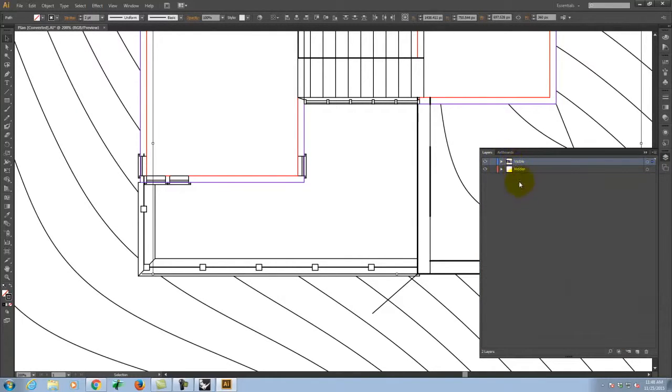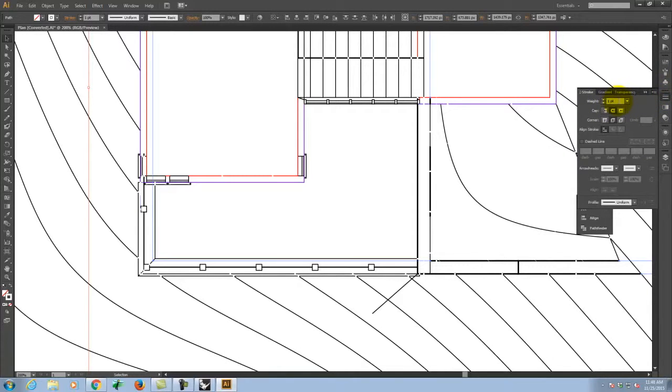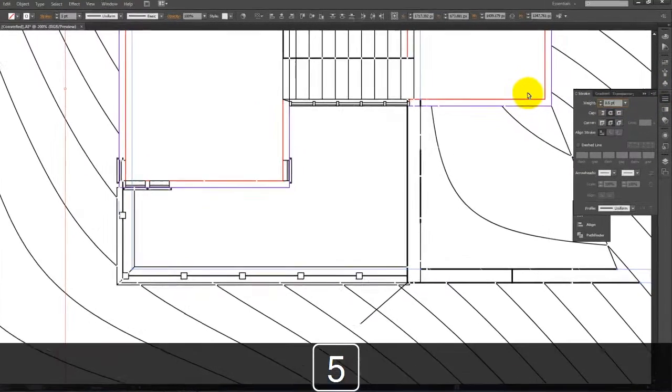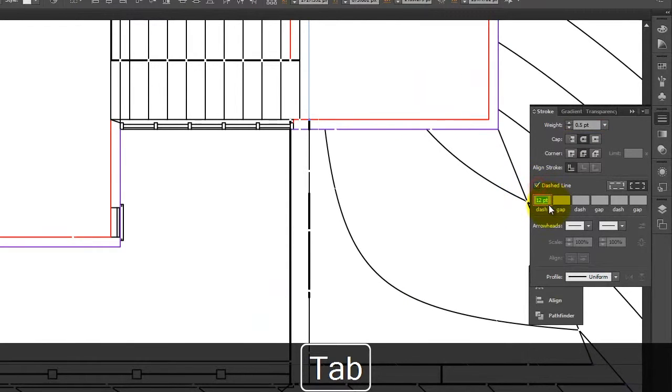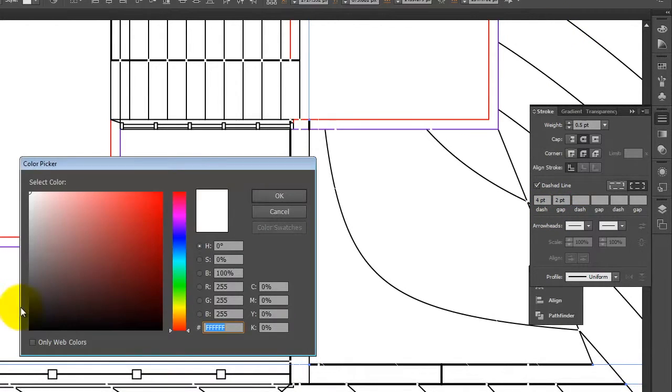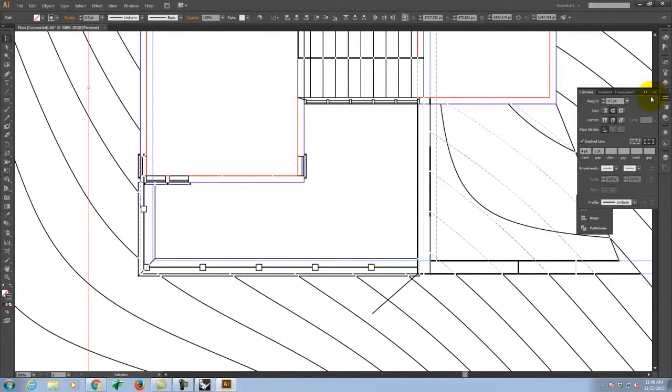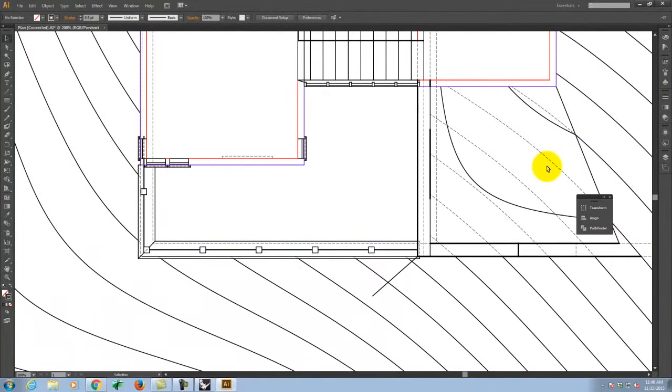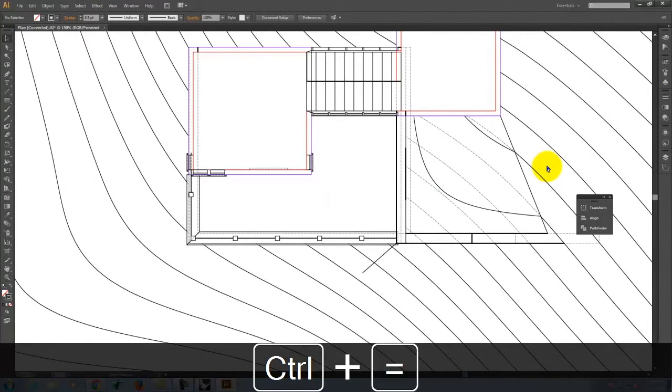It's always helpful to have them like this so that we can minimize the layer stack. But we can also select, for example, all of the hidden layers, right? Even though they're named separately, because it's inside, I can select all of them, and then we can adjust those properties. So we'll take all of the hidden layers, we'll make them 0.5 point lines, we'll make them dashed, and we'll do a 4 point dash with a 2 point gap, which is the same as what I did last time. And then we'll make all of those lines a kind of dark grayish color. And now when we select off, we can see all of those hidden lines.